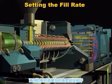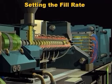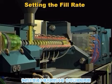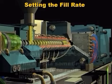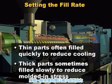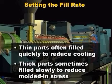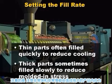The general rule for mold filling is to fill the mold as quickly as possible. Fast filling reduces the amount of plastic cooling by the mold during filling, and it also reduces the cycle time. Thin parts are nearly always filled quickly to reduce plastic cooling during fill. Thick-walled parts are sometimes filled slowly to reduce molded-in stress. However, extremes of either very fast or very slow filling result in higher stress.